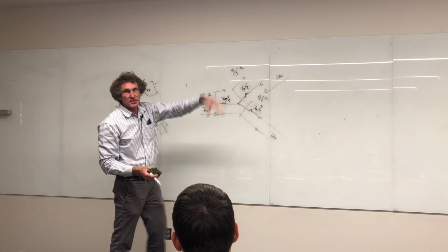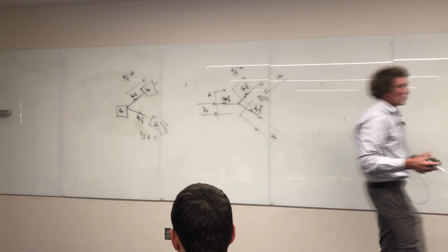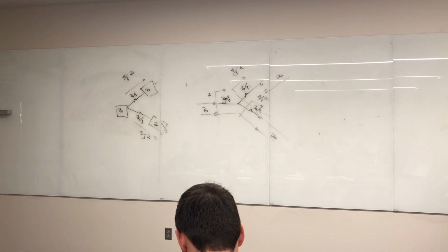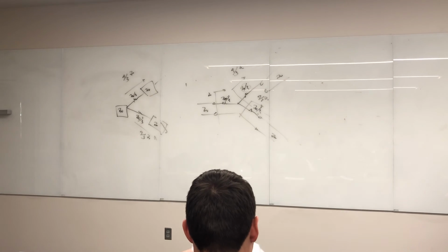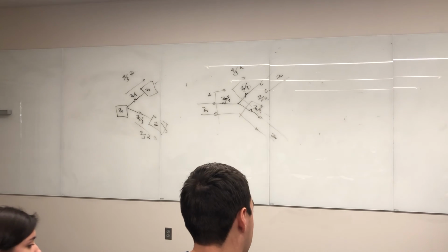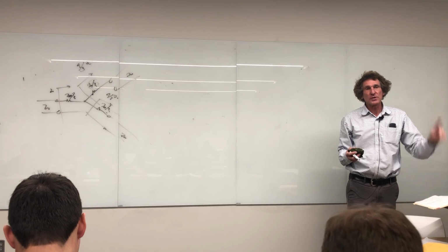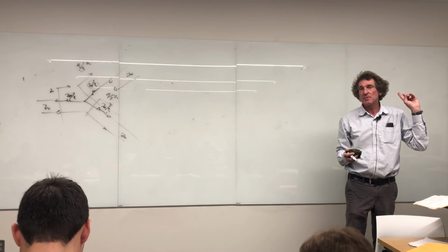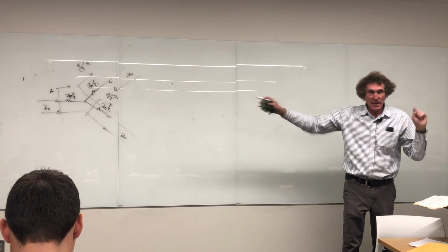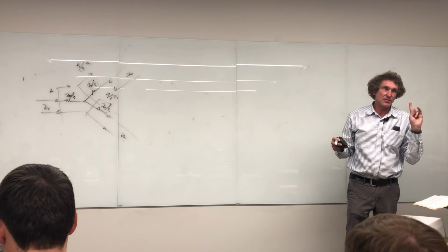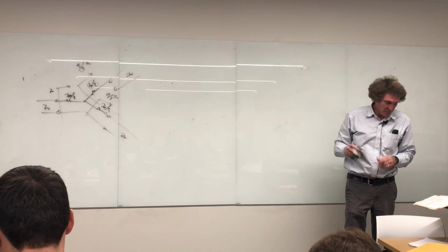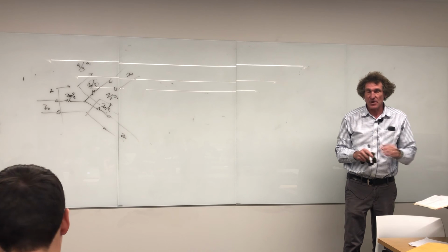So the next generation, something I'm going to cover next time, it's called a Wilkinson divider. And that uses transmission lines. This is on the top of page 571. Let me just finish with this. This is going in the right direction of giving a higher efficiency, all right? Problem with the Wilkinson divider, it only works at 1 frequency. It has to be built for 1. The resistive one works for any frequency. This is limited to 1 frequency or the whole thing goes fluey. And it's based on a quarter wavelength design that I'll talk about.